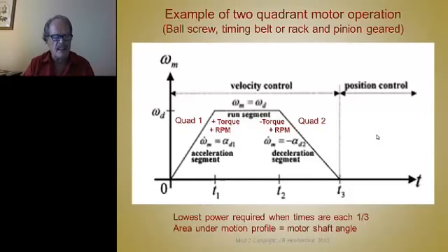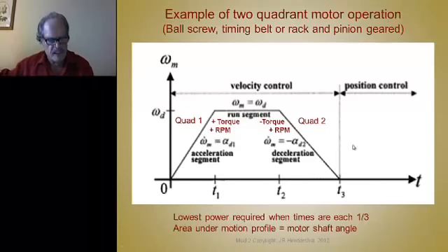So for part of that time you're accelerating, that's positive torque and speed. That's all right. Now here we're up to a speed. And by the way, this sort of a trapezoid is a very close approximation to the shape of a parabola. I guess I should have drawn one on top of here. But for an angular positional move, a parabolic move is the best, but a trapezoid makes it easy to control. So we could accelerate slower.